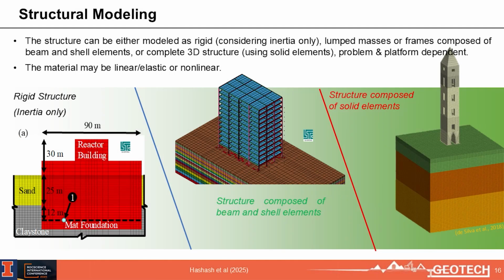a single platform. Then in terms of structural modeling, and I'm starting here talking a little bit from a geotechnical perspective, not a structural one, because if I'm a structural engineer, I would be looking at, let's put some springs to represent the soil. If I'm a geotech, I'd say, let's put some pendulums, but that is really not the way to do it. If you want to do a true soil structure interaction model, you need a software platform that will allow you to equally represent with a similar fidelity both the soil and the structure. And so that becomes very important.